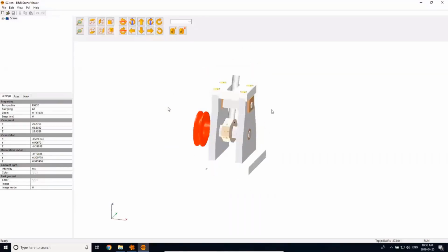So we see we've gone from bringing in our CAD into MapleSim, creating a model that makes sense or is of interest to us, has the dynamics that we care about, generating an FMU, and then bringing it into Automation Studio, having some parameters that are tunable, having inputs and outputs, and also being able to see this 3D visualization.